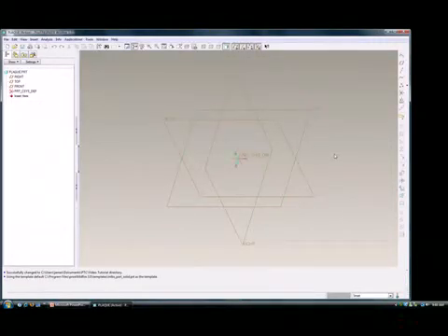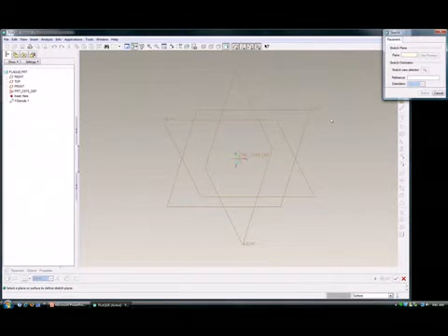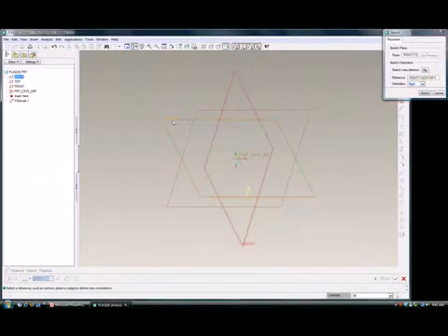The first function of Pro E we need to use is called the extrude function, which we'll use to create the base of this block here. This is the shortcut to the extrude function. Hit the extrude button, click placement, hit define. We will select on which plane we want to extrude the block. For me, I'll just use the front plane. Click on the front plane, hit sketch.